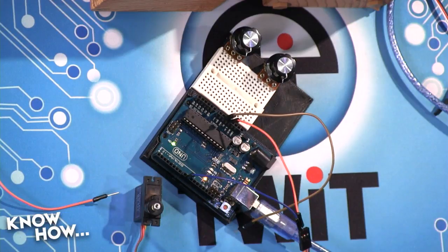In fact, if you look at the lights on the Arduino, they start to get dim. Every time it gets towards the end, they dim because it's pulling a bit too much current. So what would you do if you wanted a larger servo? Have another power supply. You would have an independent power supply.